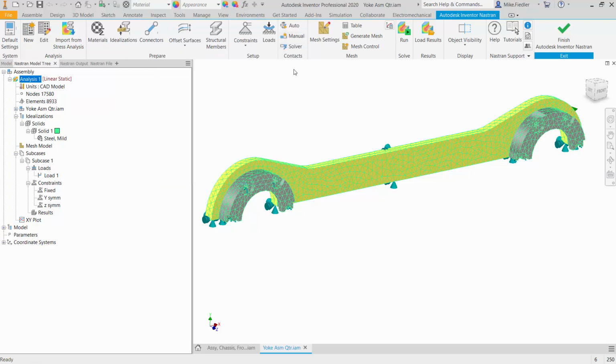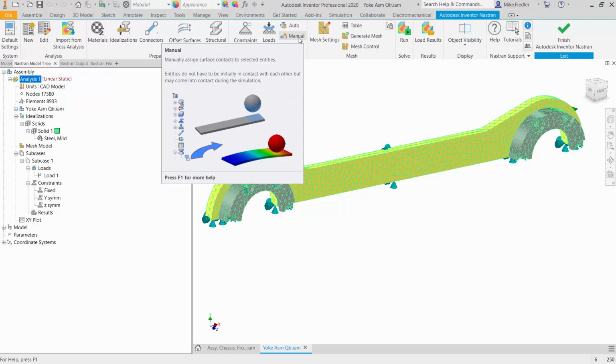And it's nice, you can see in that image that they have split up, for instance, the top surface of that cantilever beam to isolate where the contact is going to happen. I mentioned that in one of the slides earlier in the presentation, that you might want to do that just to isolate the amount of contact that you might have in the analysis.